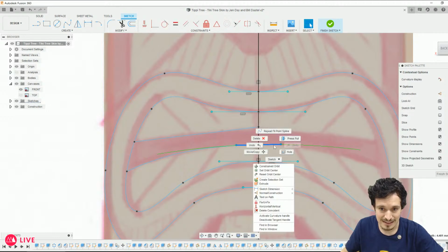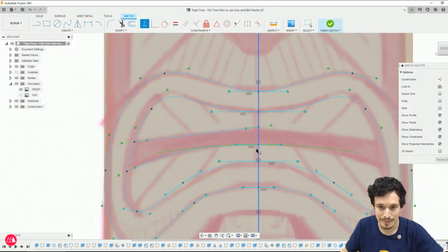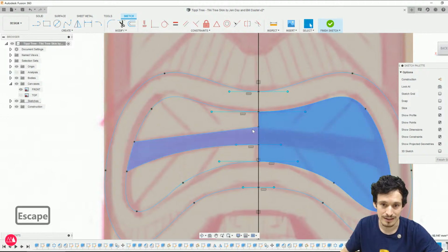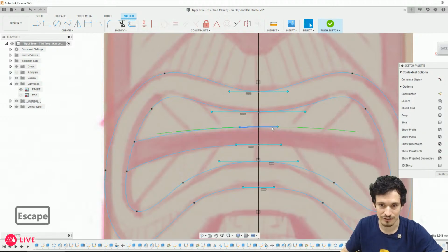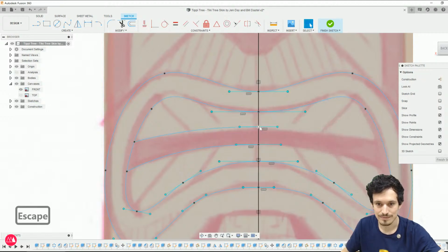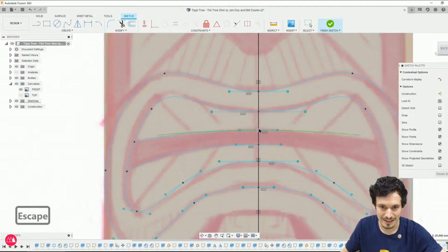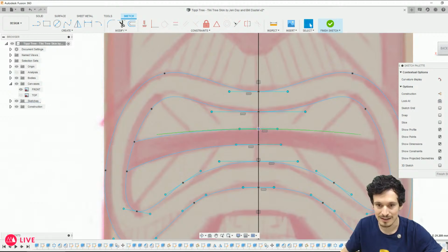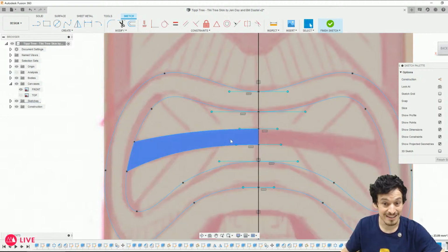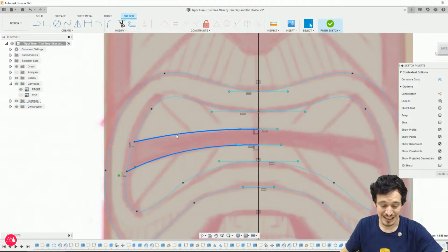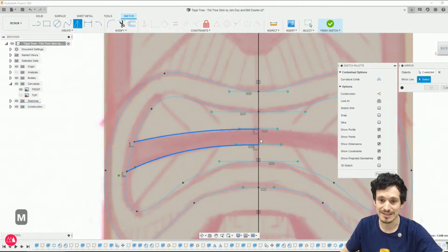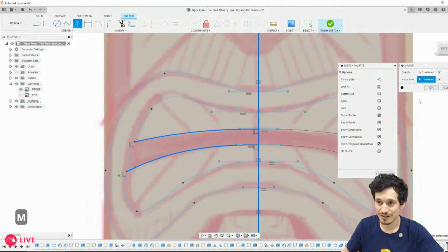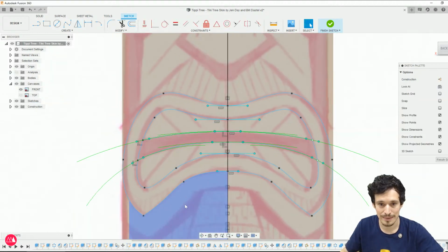Once again, I'm going to take this spline that meets the mirrored point and make that horizontal so it's a smooth mirror. I cannot stress this enough, only because it's the only actual tip I've given so far in this stream that I think could be useful to people. All right. There we go. Look how nice and smooth that curve is. That's because the spline literally only has a control point at the beginning and end. Generally, with splines, you want to have as few points as possible to make your life easier. All right, there's the mirror.